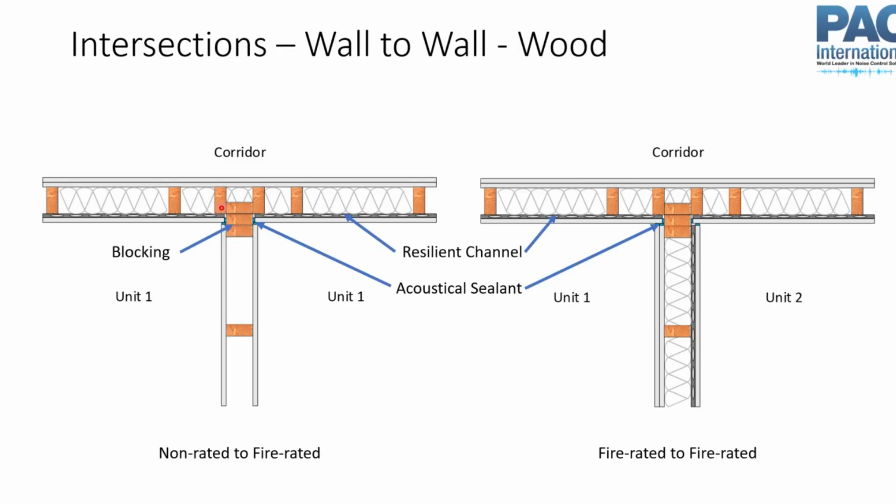But this is also, we've got a long path. We're going to try and minimize our weak links. So we have this long path, and it's got to go through this drywall, then this 2x4, then these 2x4s at the end of here. There's going to be some reduction in the sound through each one of these junctions, and the idea is that there's enough here where it's probably not an issue.